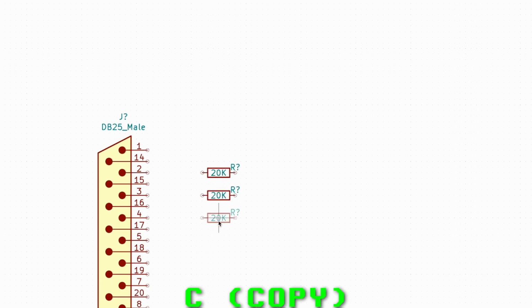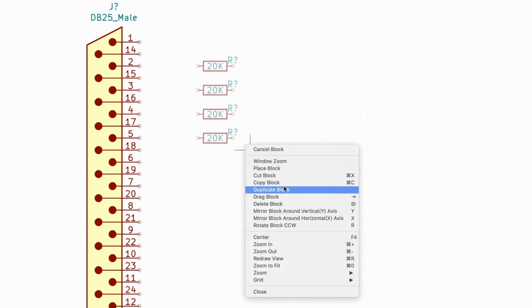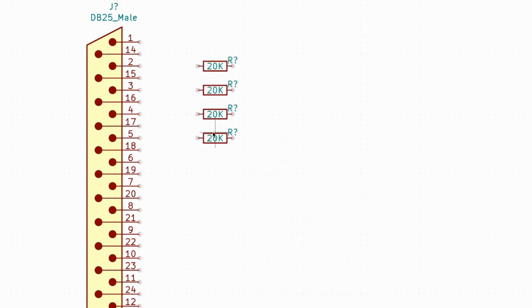That's kind of cool. Now I want to copy this. Let's move the resistor there because we're going to have a couple right next to each other, so it's more legible. Click, hover on the resistor or component, click C for copy. Boom, C, boom, C, boom. Let's block everything. Copy block, that's Apple C in my case. Paste.